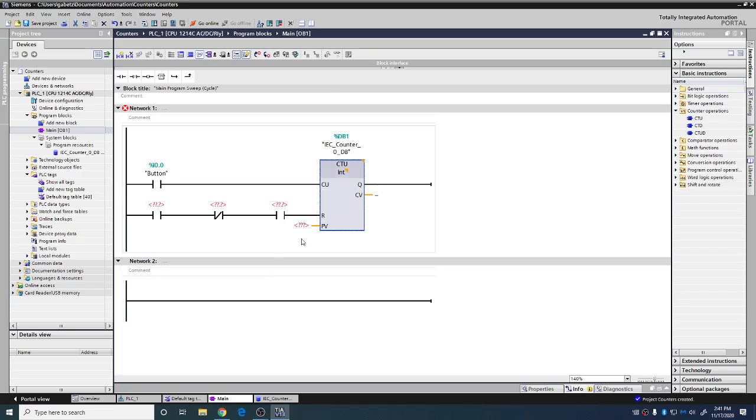All right. So if we hover over this, I can leave my mouse there. It says INT, word, or implicit data type conversion possible. So an INT is an integer. Any integer would work. So if we had a tag for an integer, we could just type that tag in here, and then we wouldn't have to set it specifically at this counter, which is kind of nice.